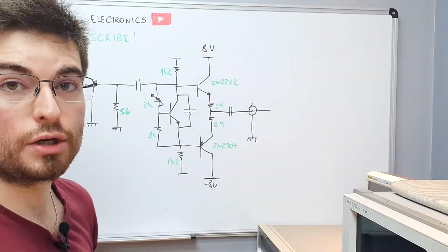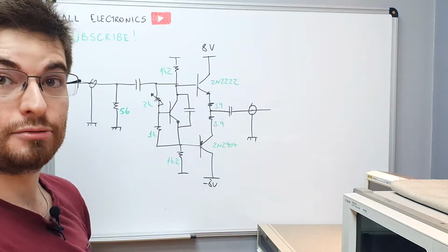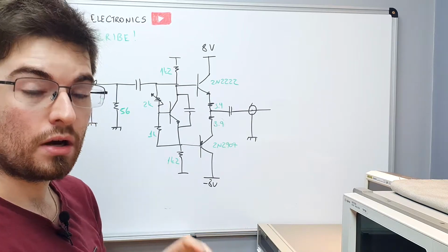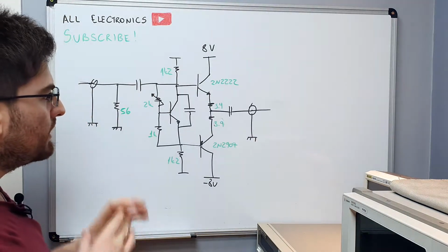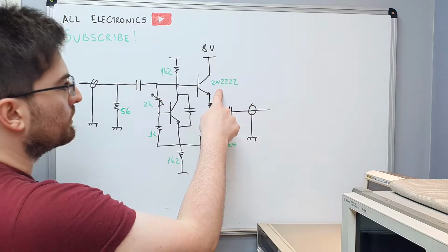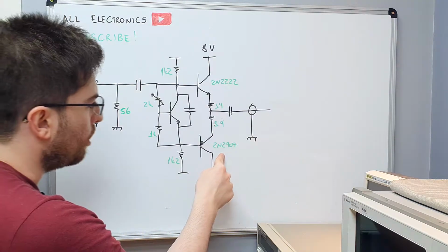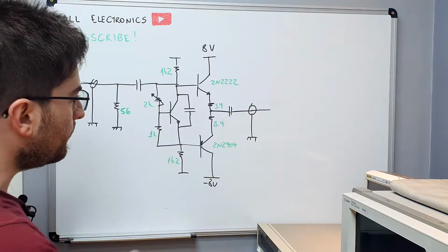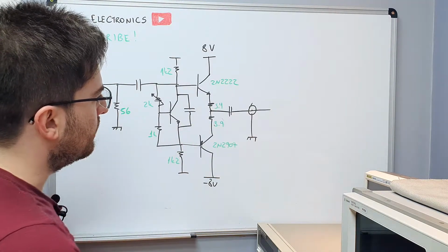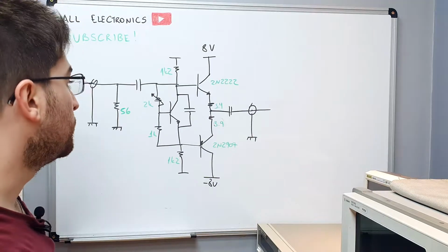So guys, this is the circuit we're gonna use to see this working and to see the transition between class B, class AB and class A operation on the bench. This is a very nice and very simple circuit. We have the NPN transistor, the classical 2222. Here you have the complementary PNP. For the output resistors, I chose 3.9 ohms, a small resistor that worked really fine.